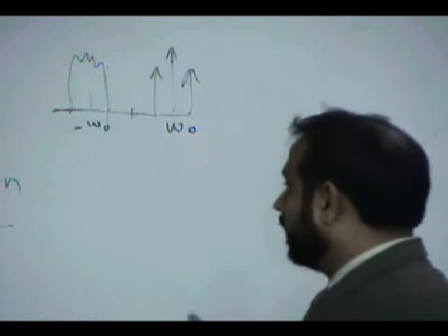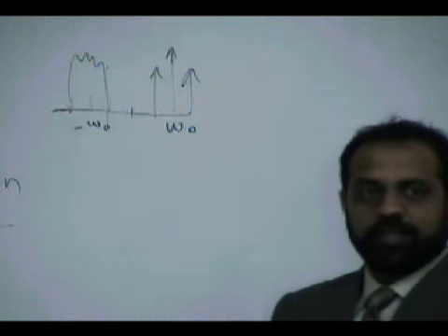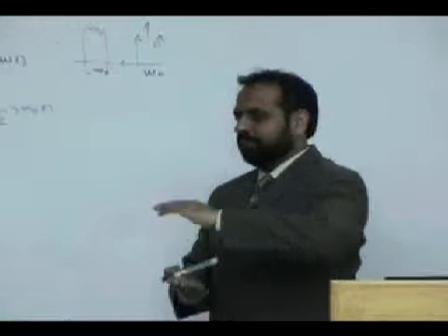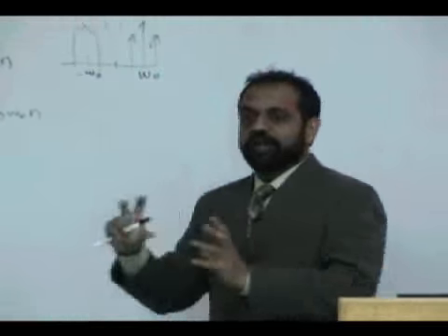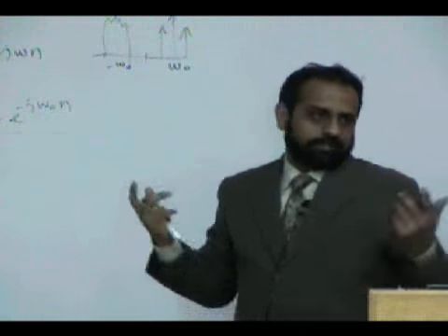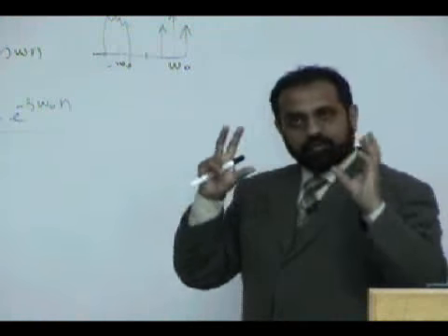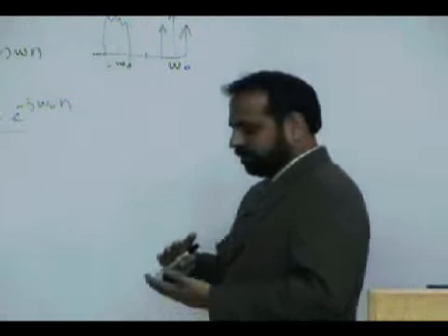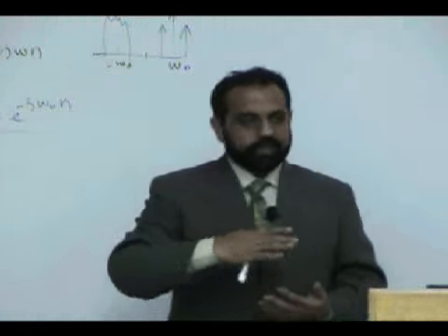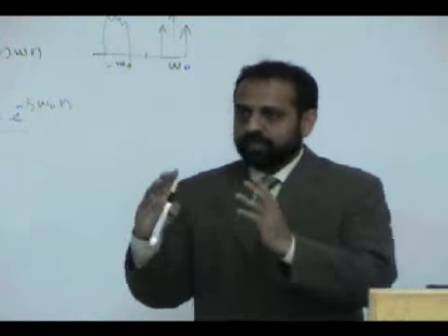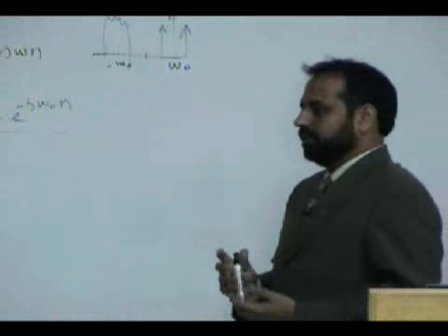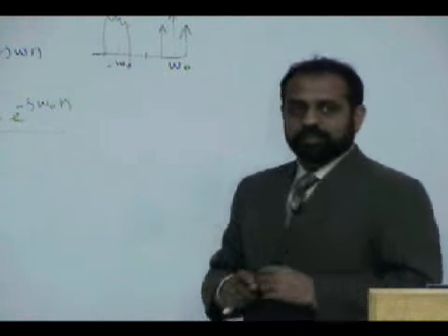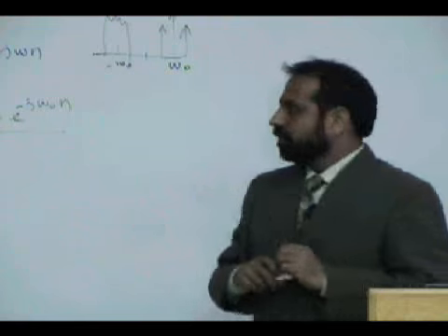And now remember that a linear and time invariant system can vary the magnitude and phase of these complex exponentials. Okay, so you have all these exponentials, and then you have a way to eliminate them, to amplify them, to move them left or right, and that is what a system does to complex exponentials. This is where we left.